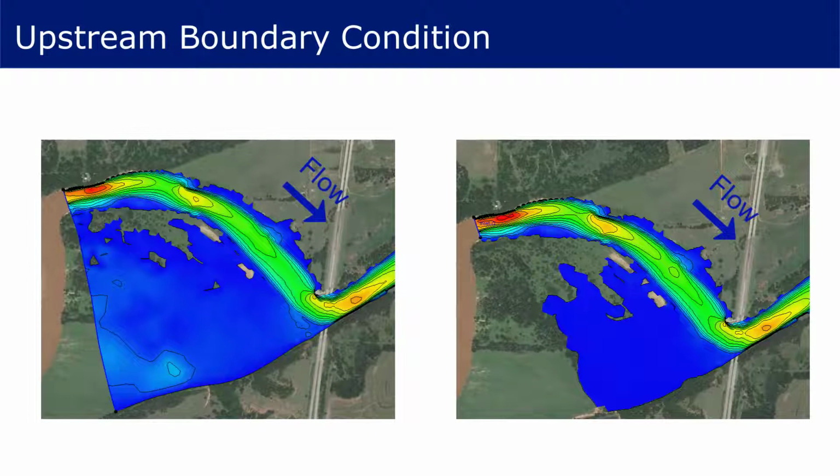The upstream boundary of the model extent defines the location of the upstream boundary condition. In defining the upstream boundary condition, the modeler prescribes the width of the boundary arc and determines how flow and sediment enter the model domain. Care should be taken to make sure the boundary arc width and distribution of flow matches the natural condition of flow in the channel and floodplain.